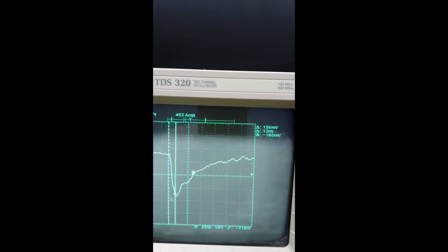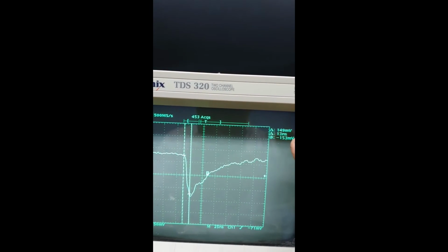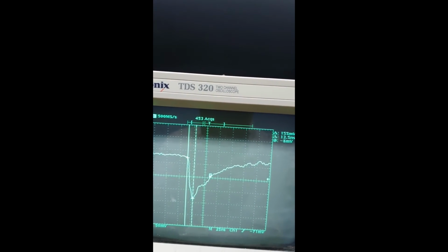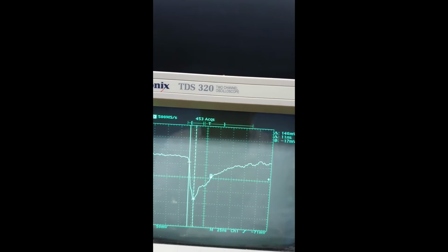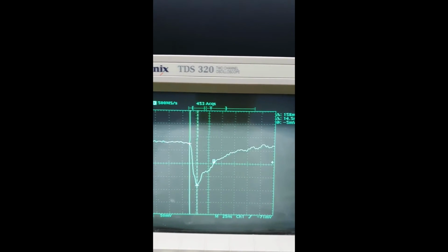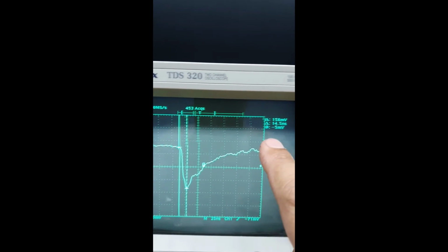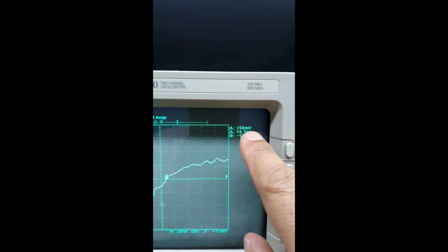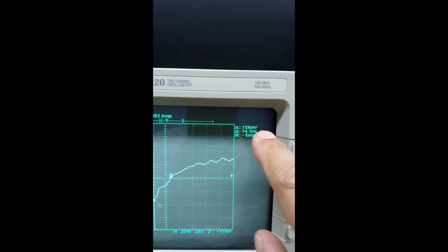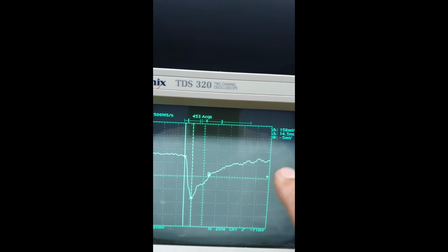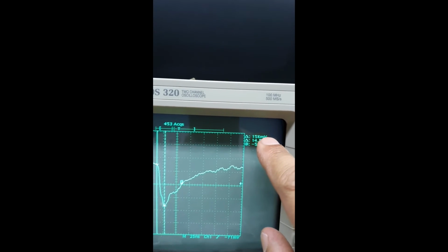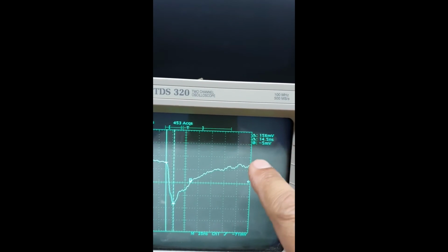So this is now here, say 149, this peak here. So I have here the voltage values: 158 millivolt, then 14.5 nanoseconds is the front time. And now if I take half of this peak value, that is 75, 76, like that, that will give me the tail time.